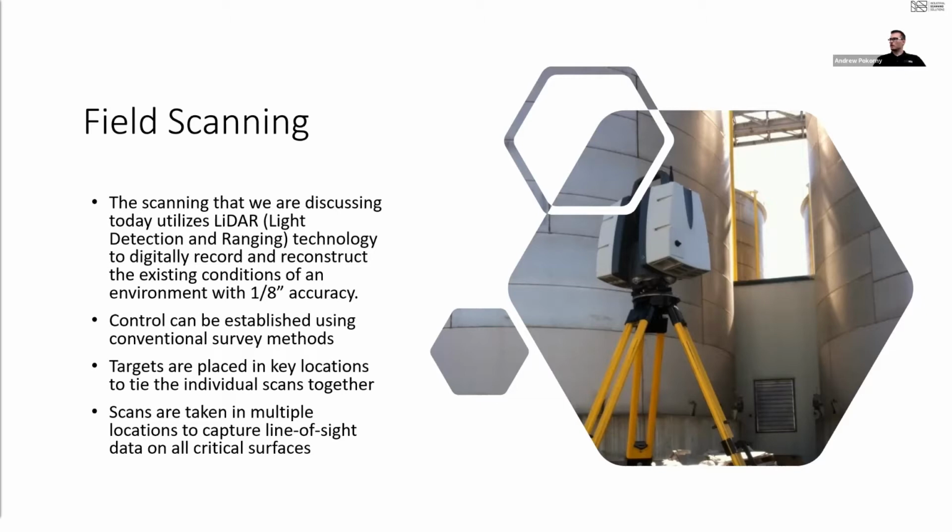And we being surveyors originally, really made it a point to say that the information that we capture is all locked down and as tight and true to reality as possible. So we use survey tools in order to establish control throughout the site using traditional survey methods. We'll lock into a plant coordinate system or to whatever coordinate system that they have on site for the project, and add control points throughout our work area to verify that we're taking our resulting point cloud and deliverables down the line and fitting into reality.